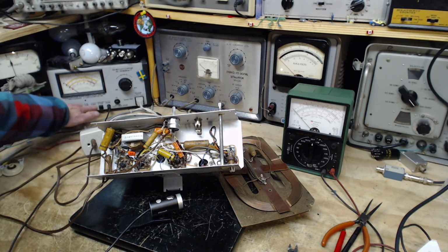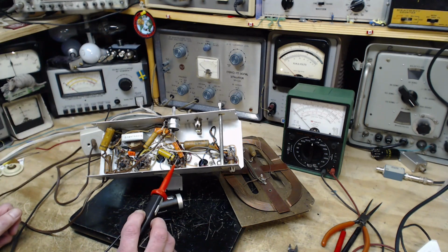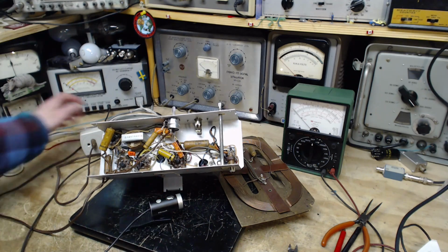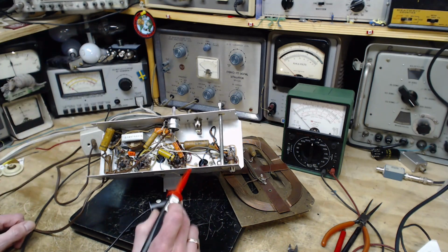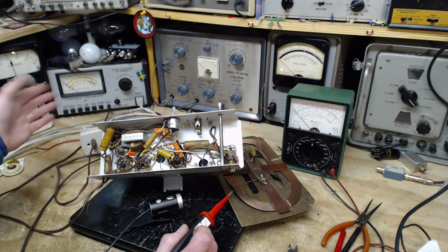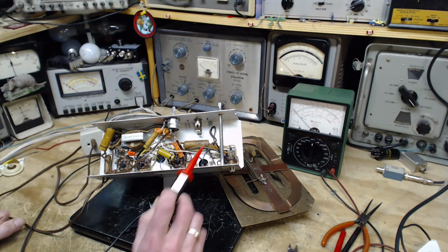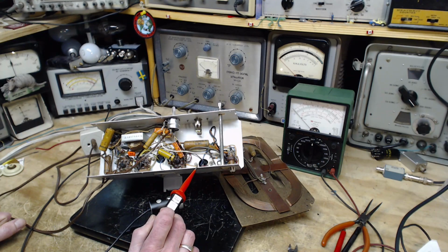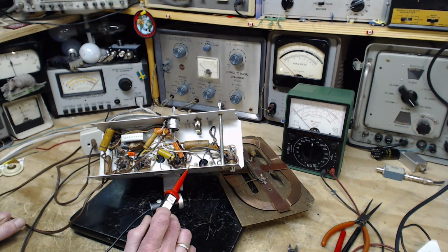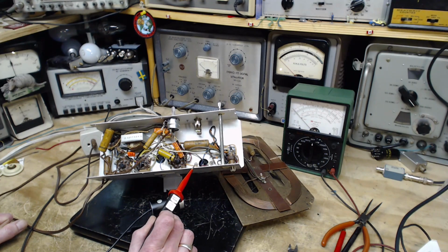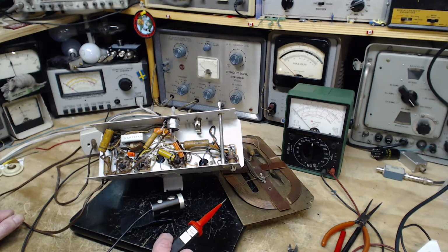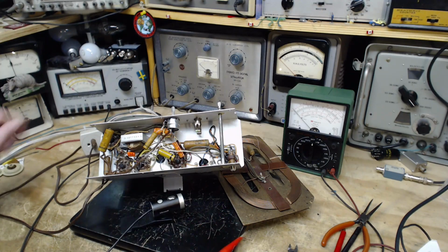Okay, so we'll start high side where we got no reading last time. Still no reading. Push the button. Nothing. Other side. High side, low side, it's just one side and the other side. Here we go. Still goes right over just like it did. Question, am I doing something wrong? Or now it's showing that that capacitor will leak way beyond the 500 microamps that is suggested.